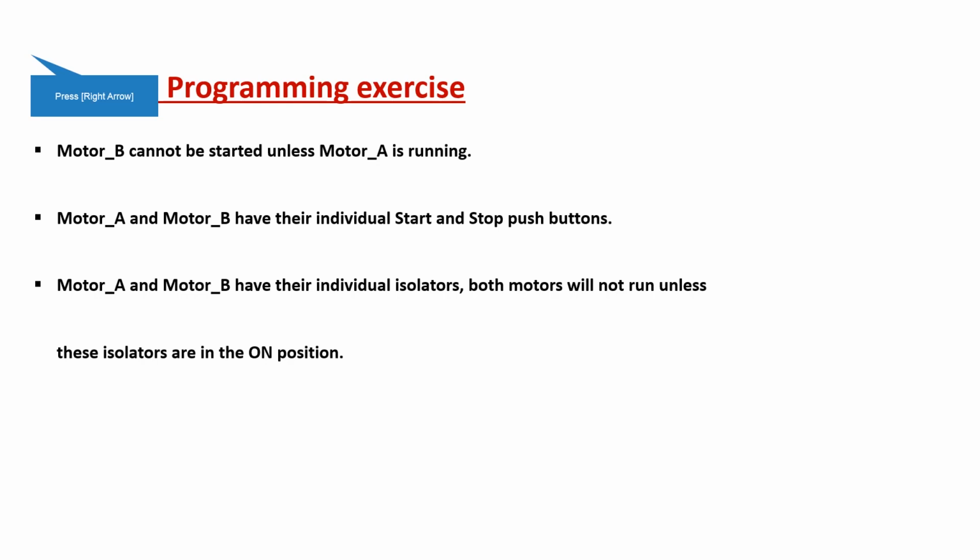The PII must be updated with the state of the inputs, in this case the start and stop instructions, whether it's 0 or 1. Then it creates an image which is looked at by the CPU, and the CPU executes the instructions based on the PII.